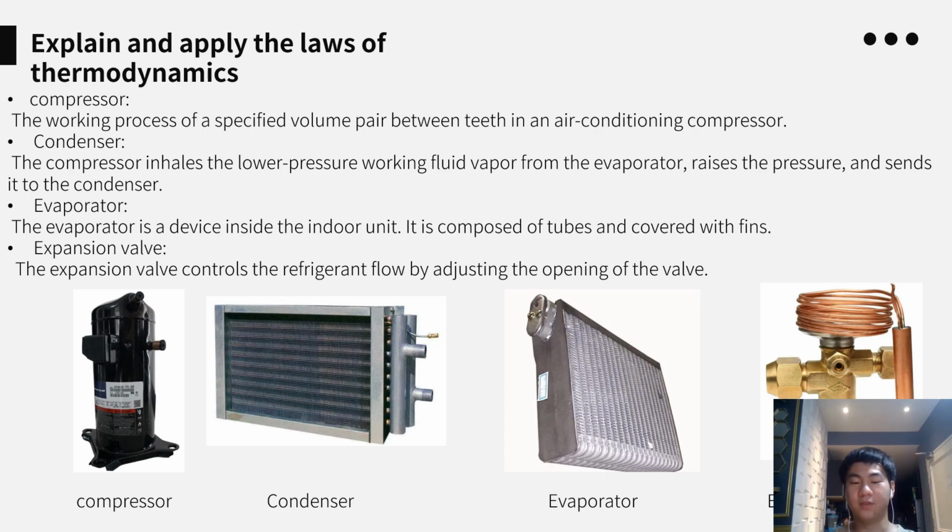The third part is the evaporator. It concentrates the solution or separates clay or particles from the solution by heating. It is mainly composed of a heating chamber and an evaporation chamber. The heating chamber provides heat to evaporate the liquid, and the evaporation chamber can completely separate the gas phase and the liquid phase.